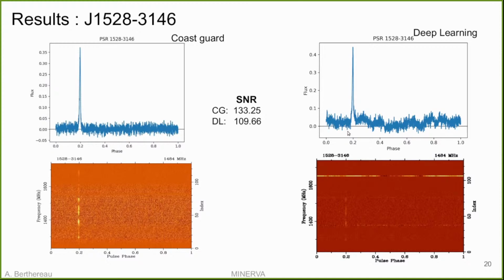And this kind of noise is problematic because when you are doing the cross-correlation in the frequency-phase domain that we are using for the TOA, you need to have the cleanest pulse possible, and this little sinusoidal noise is giving us some trouble for the TOA.